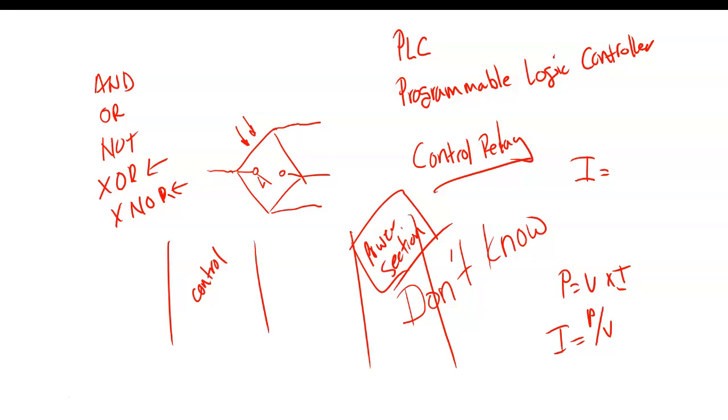The PLC, the electronics in the PLC operate off of DC. So if I use AC out here, I have to convert it to DC for the PLC. So why not just start off with DC, 24 volts DC? Then I don't have to have an extra power supply inside my PLC.